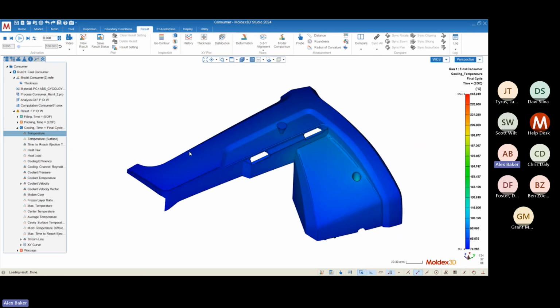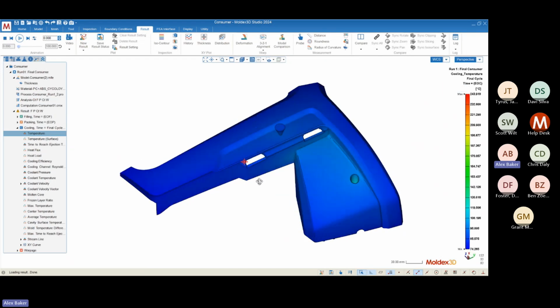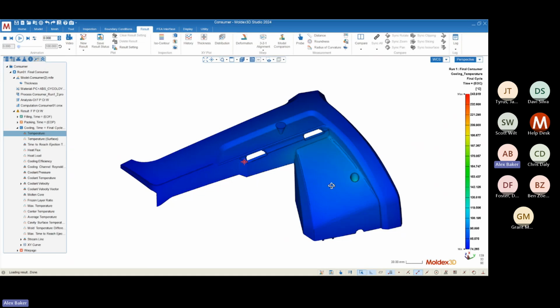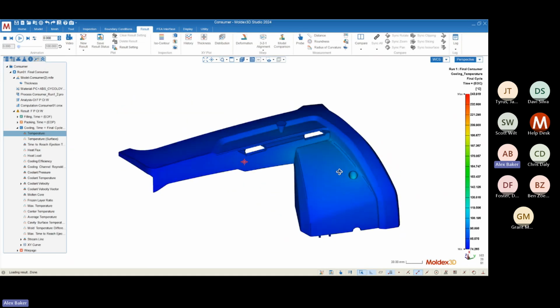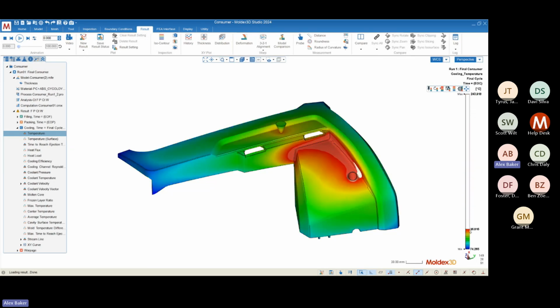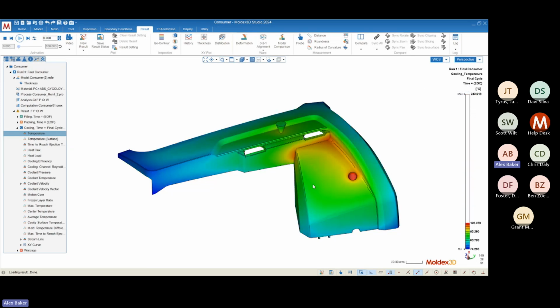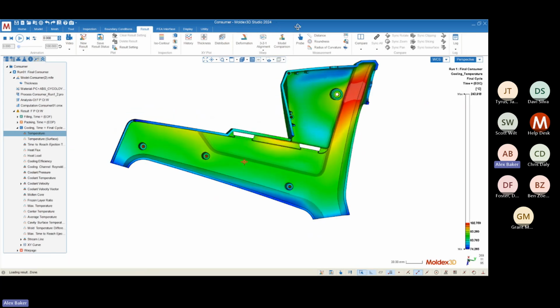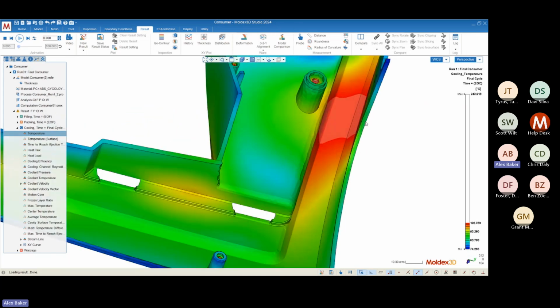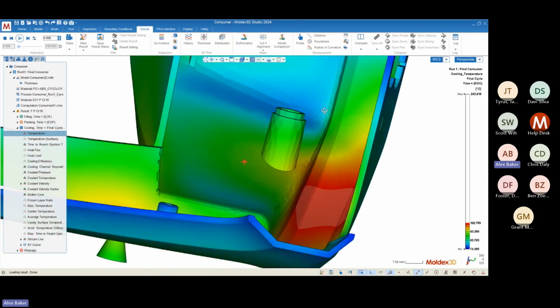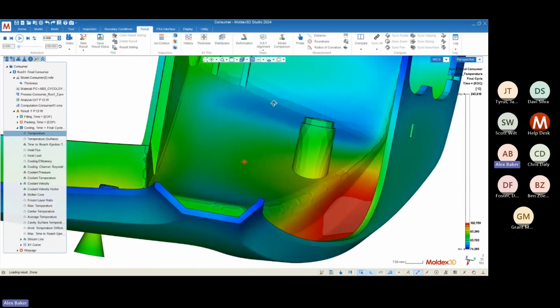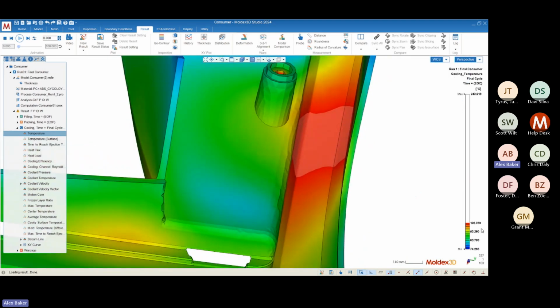All right, because the temperature is highest through the thickness of my geometry, most of the temperature distribution on the surface is going to be towards the bottom of the scale. So kind of like some of the other results that we've used, I'm just going to left click drag the maximum of my scale downwards so that I can see that temperature distribution a little bit more adequately. If you have a situation like this where you get a blotch of material that seems to be not colored at all, it just means that it's outside the extents of your range and you can just adjust the max.